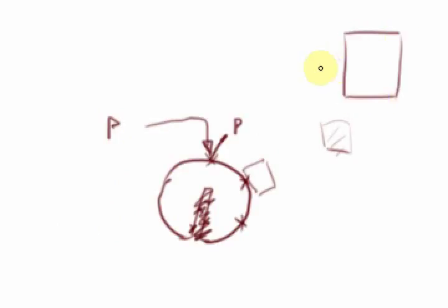Let's say we've got our catalyst particles sitting in this reactor somehow, in some beds that we've constructed, and we could simply try to remove any of this poison P from the stream that's passing through that reactor. So if we knew this was causing the loss of activity, then we could introduce additional separation units here to get rid of P.